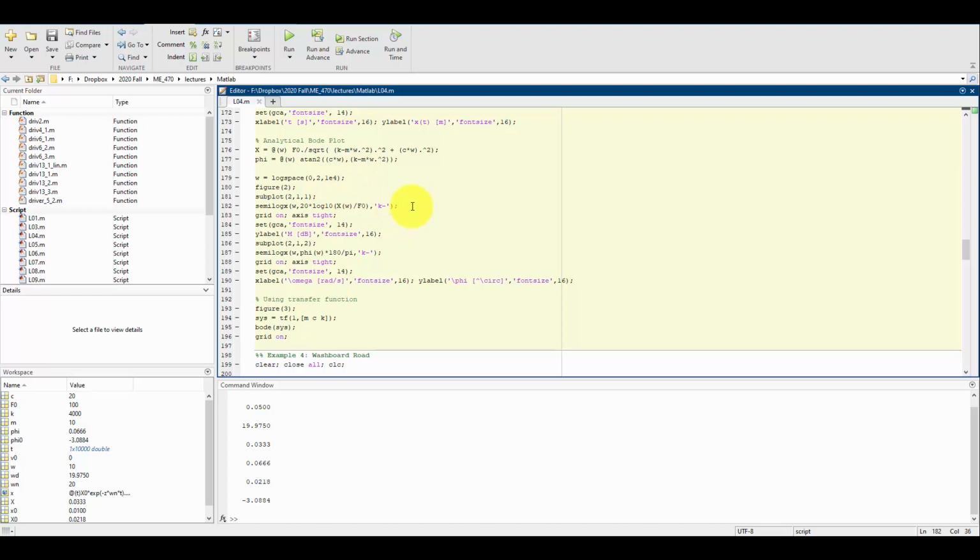So I'm going to make a figure where at the top, I'm going to plot my output amplitude, and I'm going to divide it by that input amplitude, which was 100 newtons. And I'm going to put that ratio in decibels. So I'm taking 20 times the log 10. The reason I'm representing it this way will be apparent once I create it, because this is going to match exactly what we saw in system dynamics, because really what I'm doing is analytically making a Bode diagram.